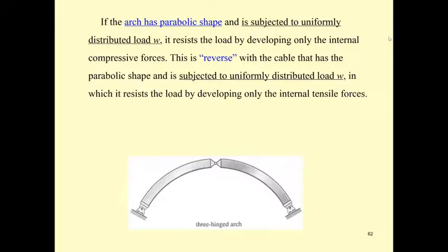This arch has a parabolic shape, and if it's subjected to a uniformly distributed load w, the internal forces developed in this arch are going to be only compressive force. This is due to the analogy with the cable that also has the parabolic shape and is subjected to the distributed load.